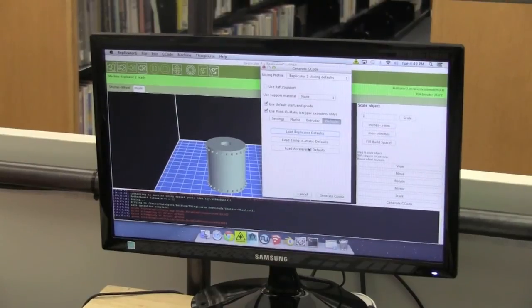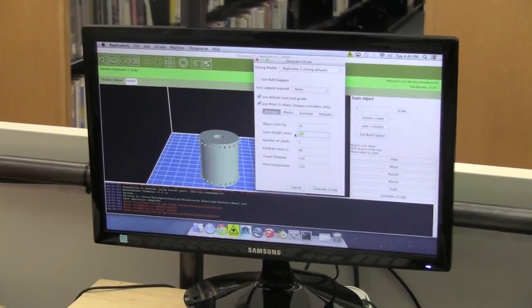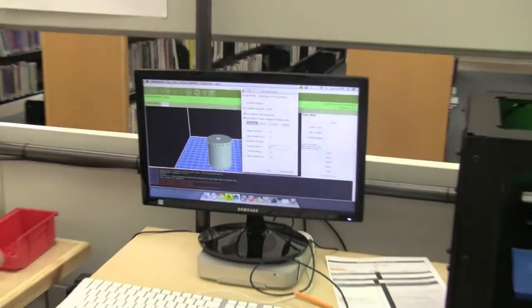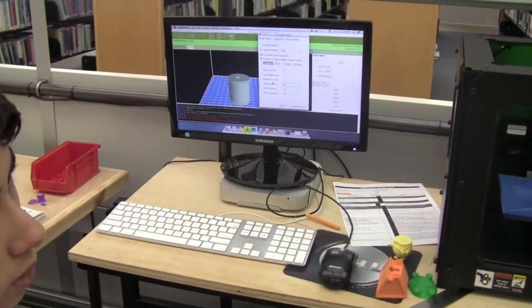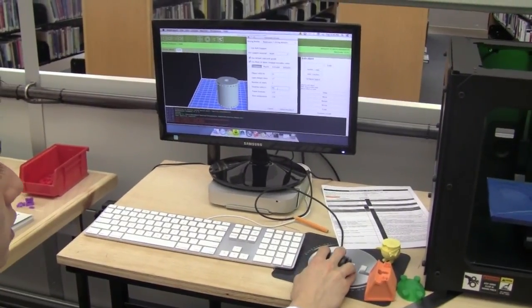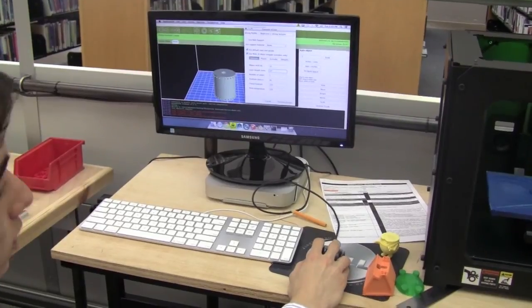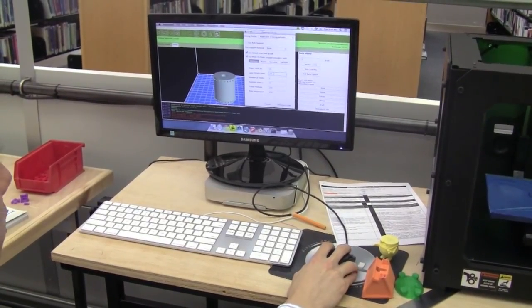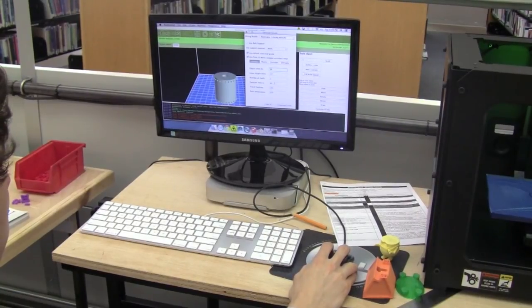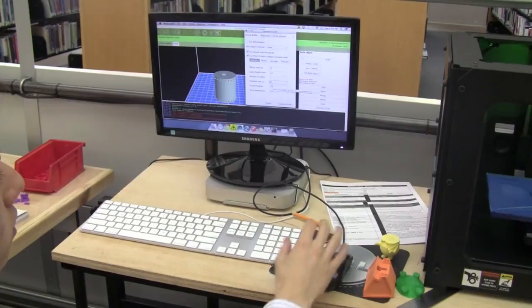Next are the defaults, like I mentioned earlier. This will give you some default settings. I don't suggest anyone use these because when you're printing something, you generally know what it's for, and these settings don't know what your model's for, so you could probably save a lot of time depending on what it is. For example, if I knew this was a moving part, I might want, let's say, a lower feed rate so that it comes out looking nicer, so that it meshes better.